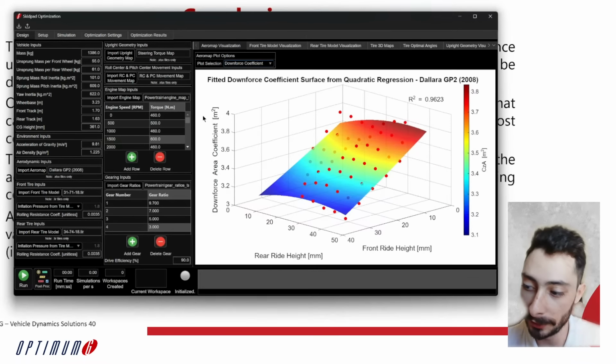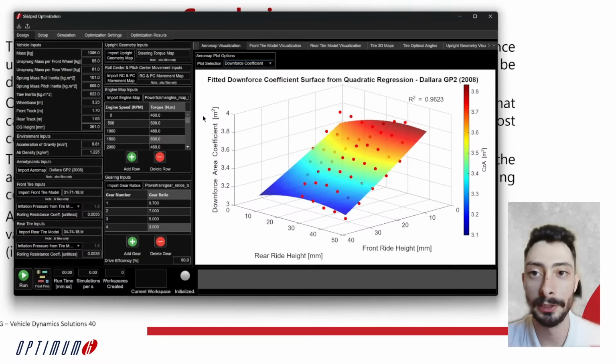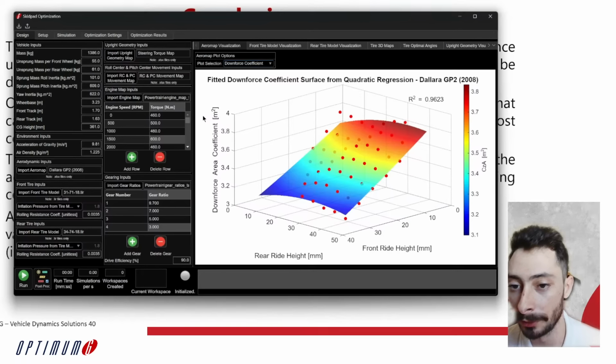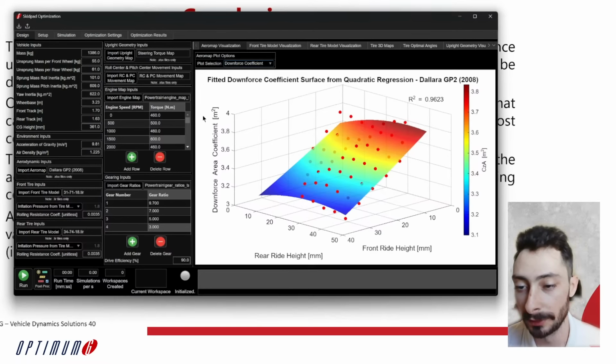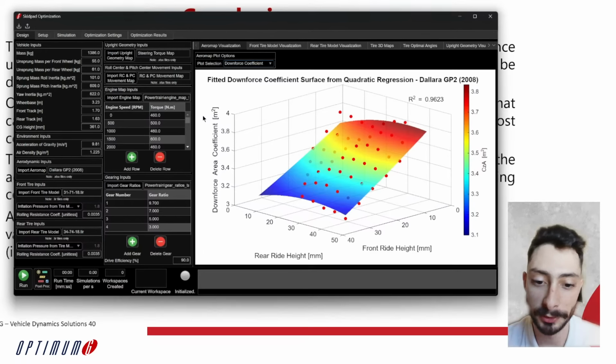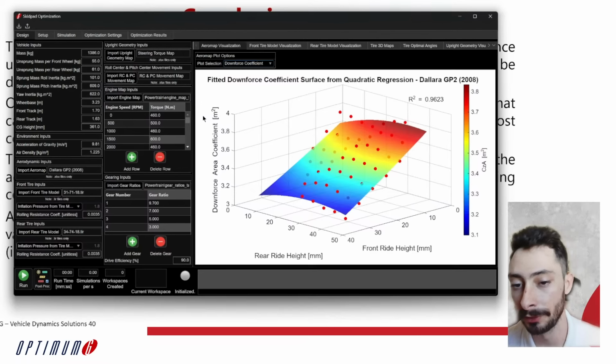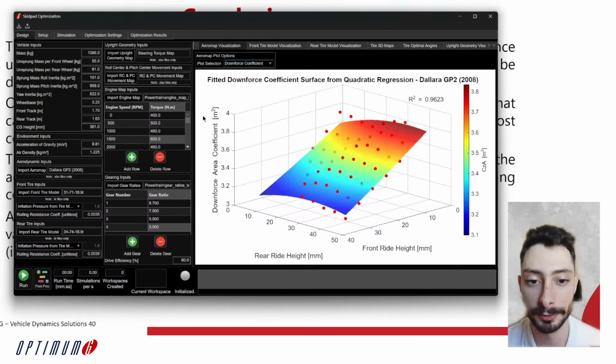It's fairly standard. You can see it in a lot of different material, not only related to racing, but a lot of the different aerodynamic models that we have from the aerodynamic map use a similar sort of interpolation. So I recommend you look into it a little bit further. But just a quick introduction to it is that it gets the points that we have readily available and interpolates this surface to get the minimum error compared to the source data that we have. And the same goes not only for lift, but also drag and the downforce distribution as well.